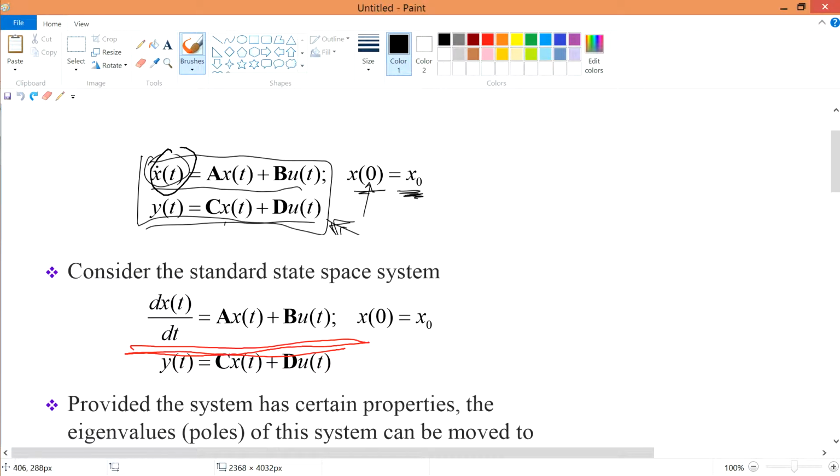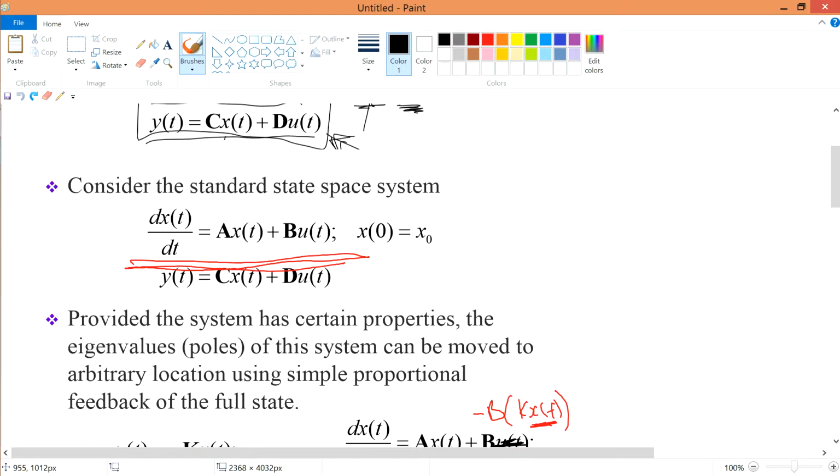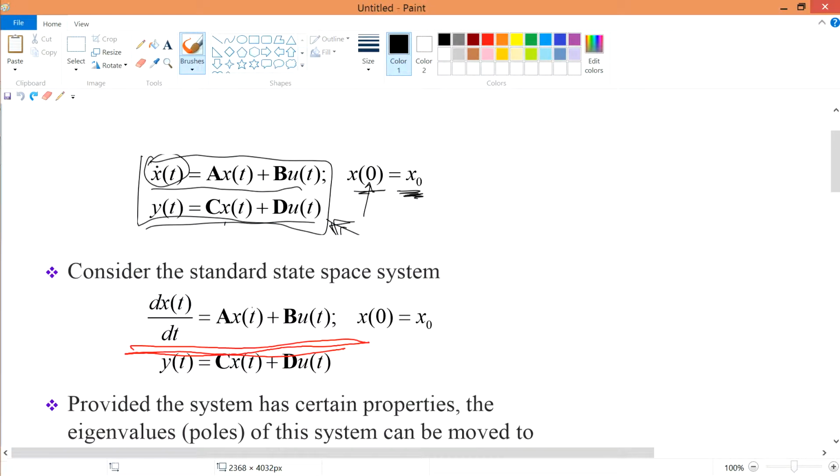The next step is the standard way of doing it: change your x dot t into dx(t)/dt. So far so good. These are the boundary conditions, saying that at time 0, x equals x naught, where x naught may be 0, 1, 2, whatever number you want. Previously, we Laplace transformed x(t) and subbed it into our Cx(t). In this case, we're going to deal with the u(t) itself.